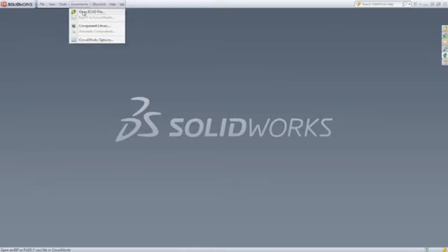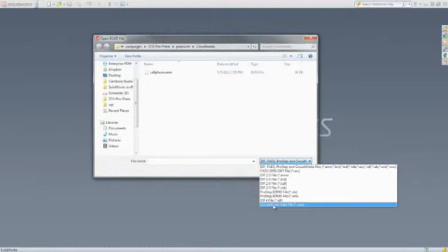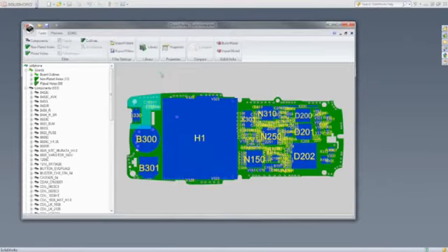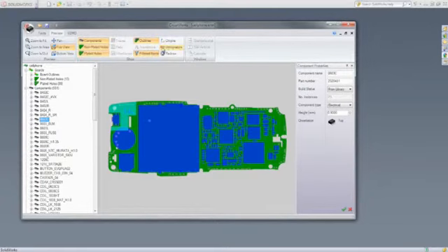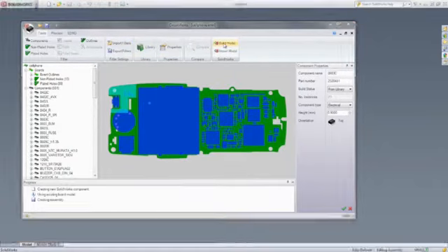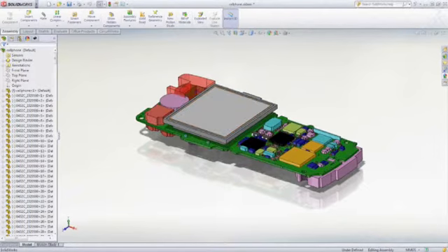SolidWorks Premium provides tools that make it easy to work with PC board and 3D scan data. CircuitWorks is a bidirectional electronic CAD translator for creating 3D models of circuit boards in SolidWorks. The dedicated CircuitWorks interface lets you open, compare, and save ECAD files with support for industry standards IDF, PADS, and ProSTEP EDMD. You can visually inspect the board, modify ECAD properties, or use the powerful filters to reduce complex features that are not required in SolidWorks. When ready, the board can be built as a 3D assembly model from the customizable component library and ready for use in your designs.